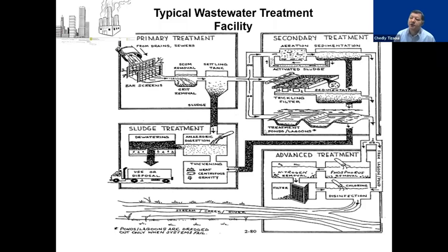If you look at the treatment process, we have the bar screens, we talked about that, grit removal, and the first settling tanks to remove suspended solids and any solids left in the wastewater. After those settling tanks, the wastewater is generally free of solids. However, there will be some solids left. You can't guarantee that these units will 100% remove the solids, but the majority of the solids have already been removed at these points. And there will be some left over, generally suspended solids, okay?